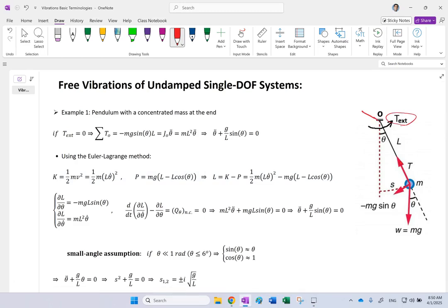And there could be some damping here, which is a kind of backward torque that is going to slow down the system. That is because this joint here could be lubricated and could have viscous friction or Coulombic friction. Now, most of the time we look at viscous friction, which is what you're going to see in my next video, where the torque here is proportional to the angular velocity theta dot times a constant c, which is called the damping constant. And that is due to the lubrication of that joint, and that is going to slow the system down. So we can have these or not.